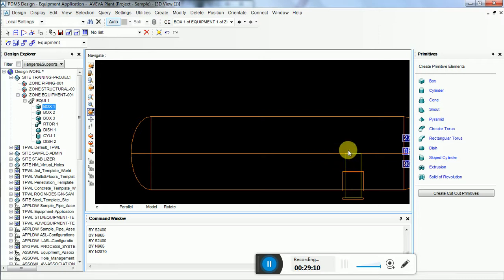You don't have to click anywhere after paste. Just give it in the command window. I have to move in the north direction. So I am giving north 2870. Okay, here it is, 2870. Hit enter. Here you see this paste comes here.